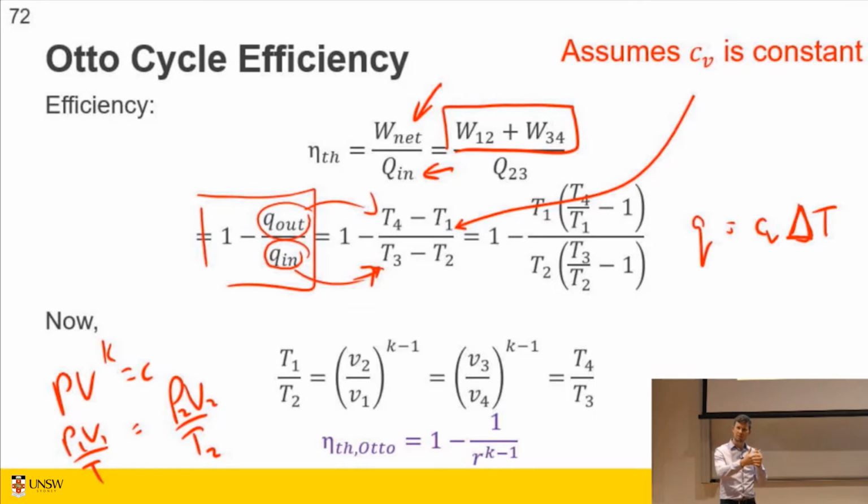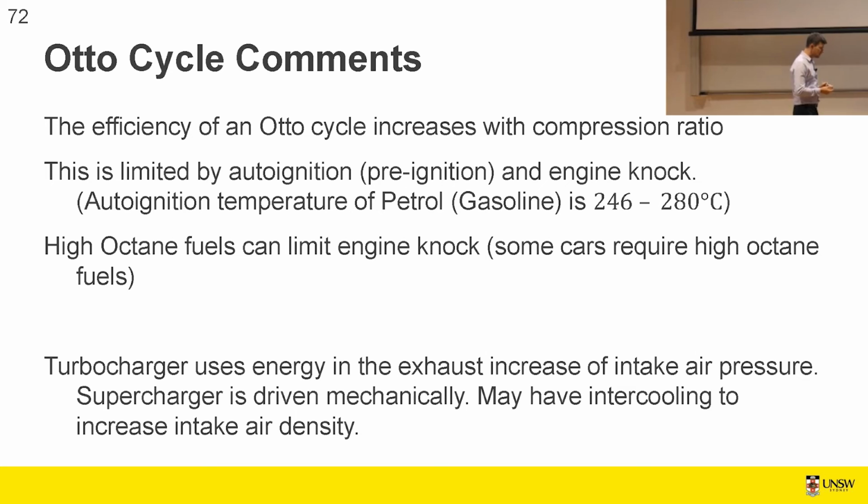Normally, it would be around the realm of 7 to 9 for just a stock standard petrol engine. And what limits that? So compression ratio improves thermal efficiency. What limits that is, in a normal spark ignition engine, you introduce the fuel into the air as it comes in, and then you compress it. You get a problem called auto ignition.